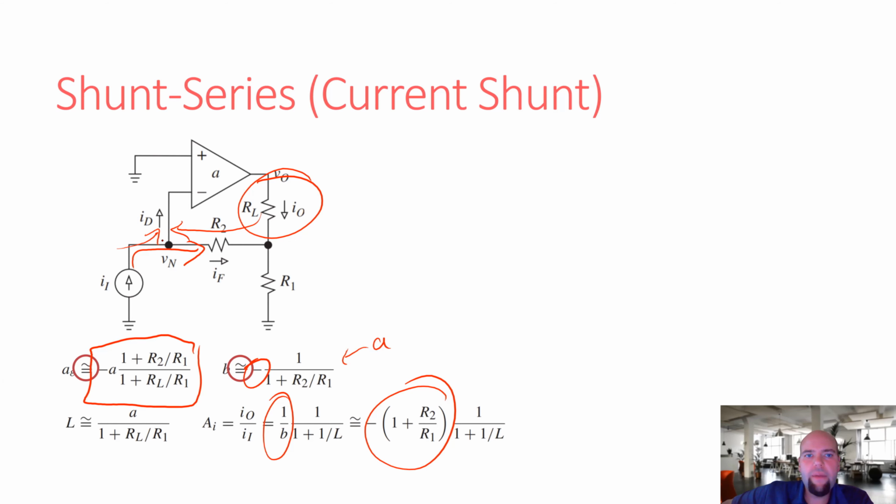So describing it two different ways is kind of important. The analysis that we go through traditionally with op amps is very different than what's actually happening at the system level, especially when we think about this as a feedback network. What's actually happening here is we are sampling an output, producing feedback, combining that feedback with an input, adding that feedback, taking the difference, right? That's functionally what's happening in this sort of system.